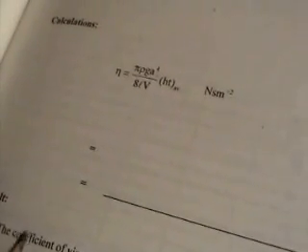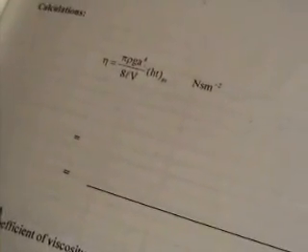Remember, the value at 20 degrees centigrade is only 1 into 10 power minus 3. For a higher temperature, viscosity will reduce. As temperature increases, viscosity reduces. So depending on the temperature in the lab, the value of viscosity may change. And depending on the quality of water you are using, the viscosity may change.